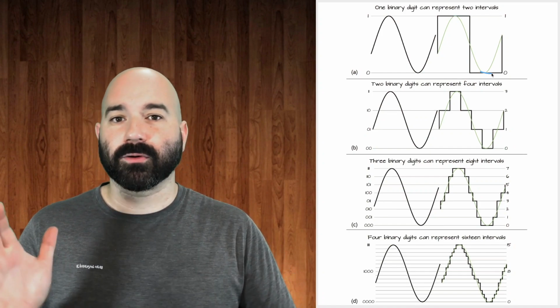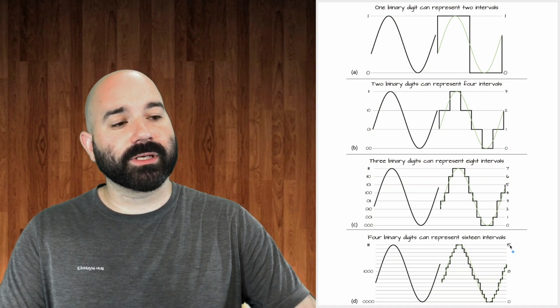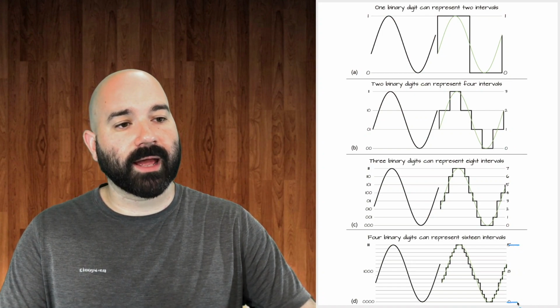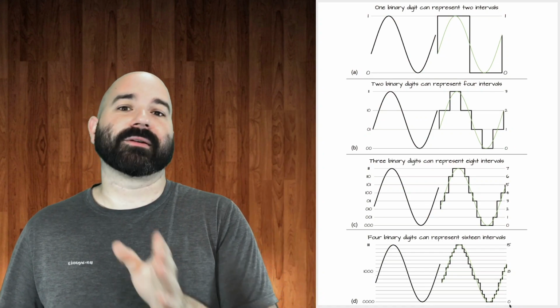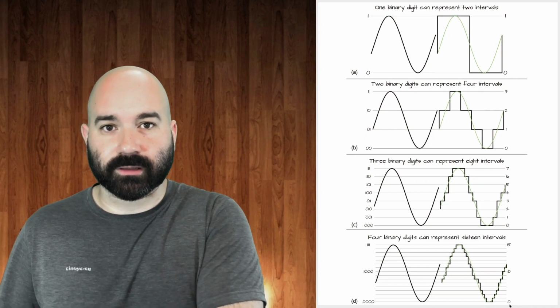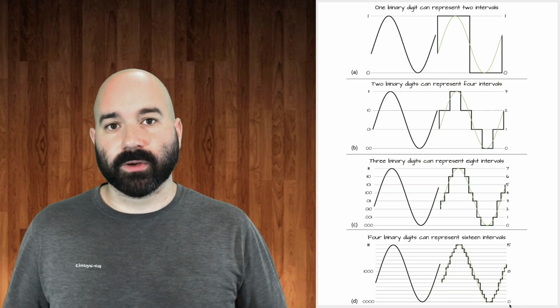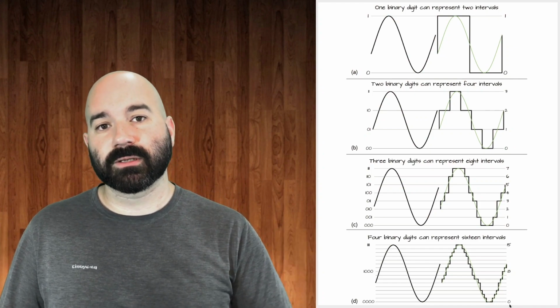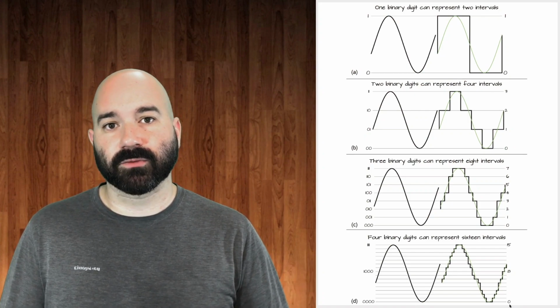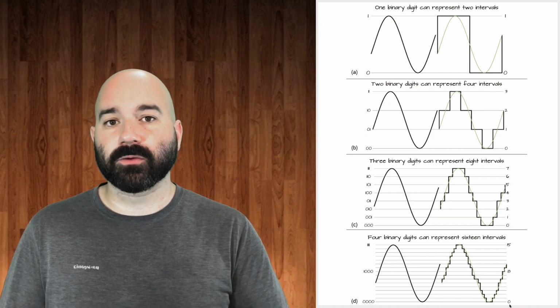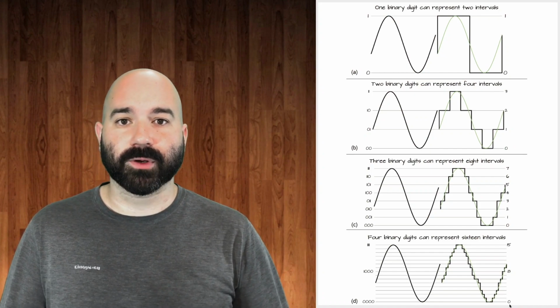There's loud or quiet. As we increase our bit depth, we can have more quantization intervals, which means we can have a larger dynamic range. We can have really loud, not so loud, a little bit loud, normal sounding, quiet, and then all the way back down to nothing. So the bit depth specifically correlates to the dynamic representation of the wave, and sampling is how accurate we are and whether we're getting those high frequencies.